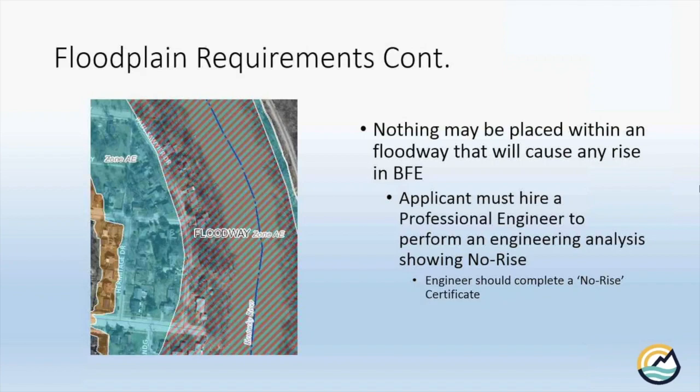So when you're talking about building in there, nothing says you can't. We just say you can't put anything there that causes the water to go up, because remember, that's where the water is deepest. Anybody who wants to develop or build in a floodway, you have to hire a professional engineer to do an engineering analysis that shows that the water elevation doesn't go up based on what you're wanting to do. That engineer has to put together a hydraulic model and give it to us along with a no-rise certificate, basically certifying, hey, I did the analysis, this is fine.